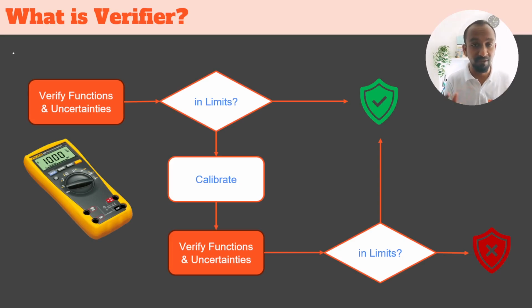the specified limits. You would try to compare your measurement against your standard equipment, let's say a digital multimeter with high precision, and you would also have some sources that will generate the necessary functions, either a voltage function or a current function, that you would connect, and you would compare against what your DUT, the unit under test, your multimeter, shows, and see whether it is very close to the standard that you have.